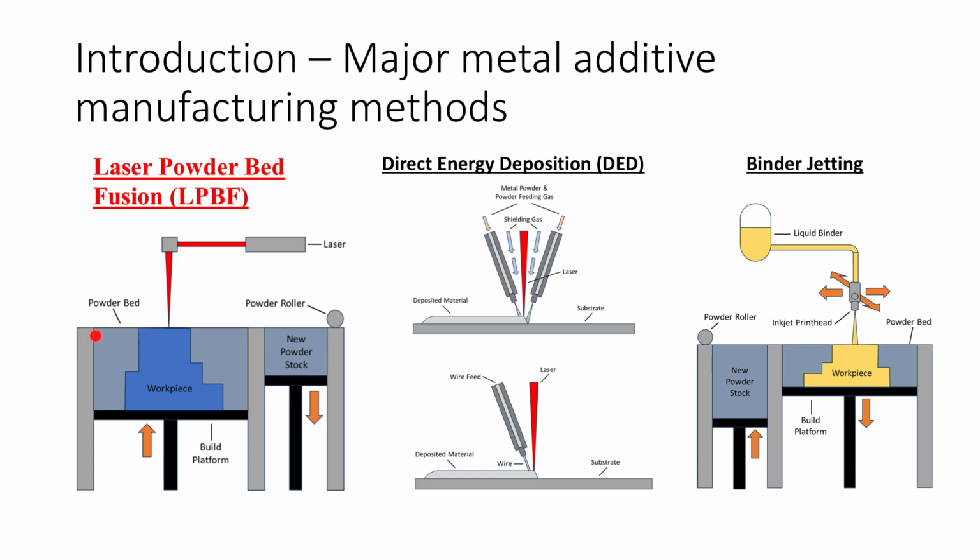So at this top layer, it is going to move around, and wherever we want to create the part, it is going to bind the particles here. Either it's going to sinter or melt. It could be laser or electron beam. And it's not going to touch the other areas.